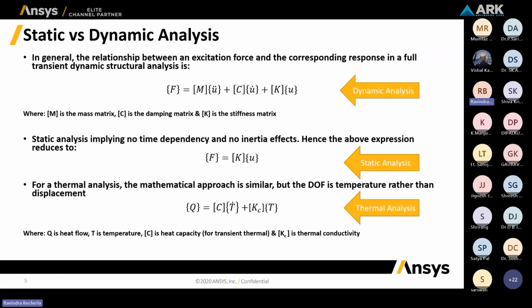If we are analyzing any structure, and the structure is not moving with respect to time, or the force acting on the structure is not varying with respect to time, then generally we consider that problem a static analysis, and this is the equation that we will solve for static analysis: F equal to K into U. F is the force that we apply, and U is the displacement that we get because of this external load F.